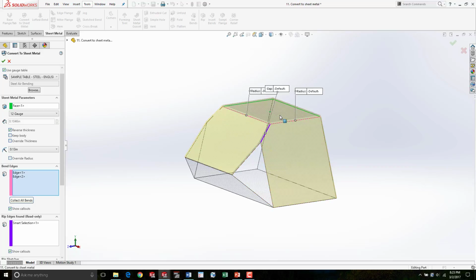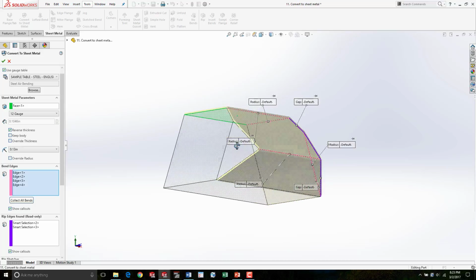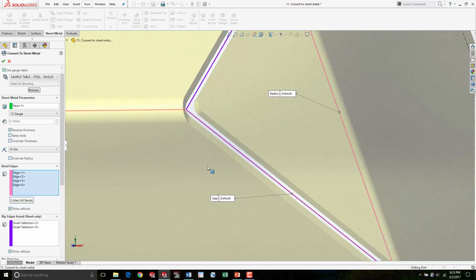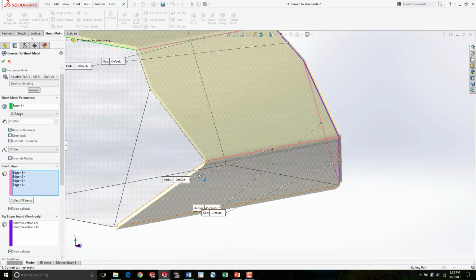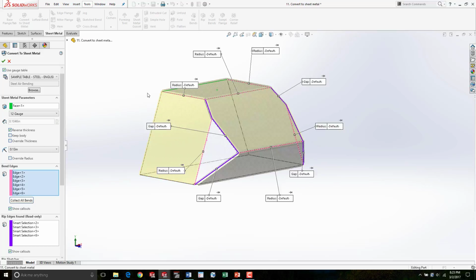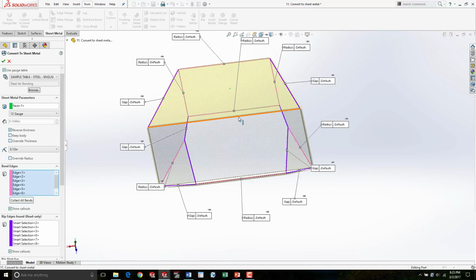So if you can follow what we've got, this one bend coming down here. Maybe we want this triangle piece attached to it. So if I select this edge here, it's going to rip that connection and build it off over there. Maybe I want this front face to be bending down to this one. Again, we can see that full rip being put into place. And when we look at this preview, we've got this full thickness going on there. So I'm just going to go ahead and add a couple more on there, so we can get this full part.